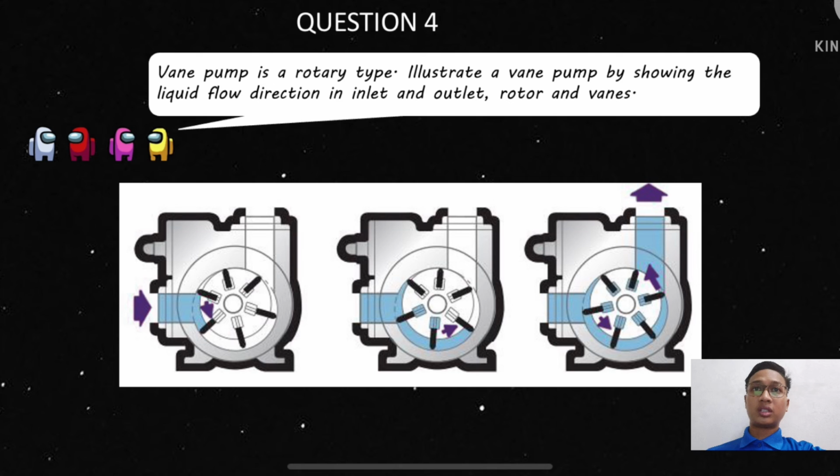As the rotor rotates and fluid enters the pump, centrifugal force and hydraulic pressure push the vane to the wall of the housing. The tight seal among the vane, rotor, cam and side plate is the key to the good suction characteristic common to the vane pumping principle.